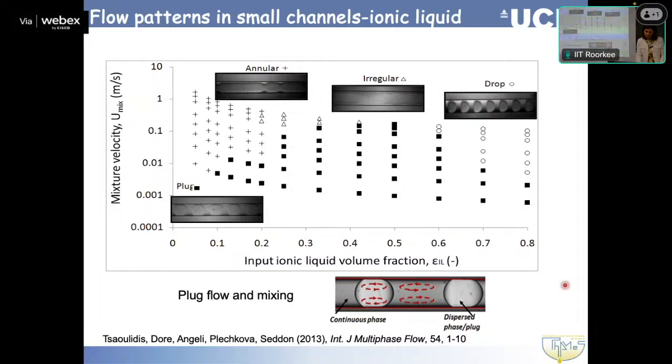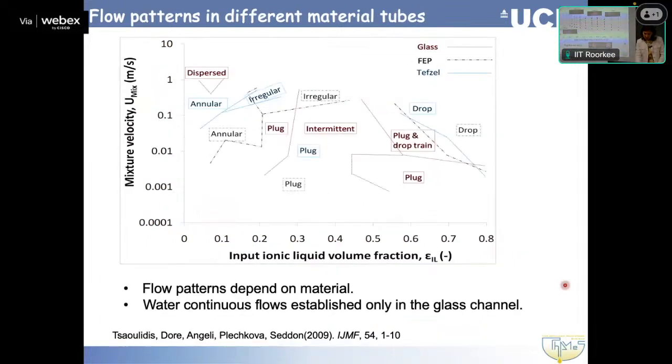So talking about flow patterns, what I wanted to show you is a little bit, again, continuing with the effect of the wall. And this is something from data we collected. We do use microfabrication for some of the channels, but having in mind also what is easy to do and how you eventually scale up at some point, we also use a lot of tubing. So instead of microfabricating something on a wafer chip or on glass, we just buy capillaries. So a lot of the results I'll show you are from capillaries.